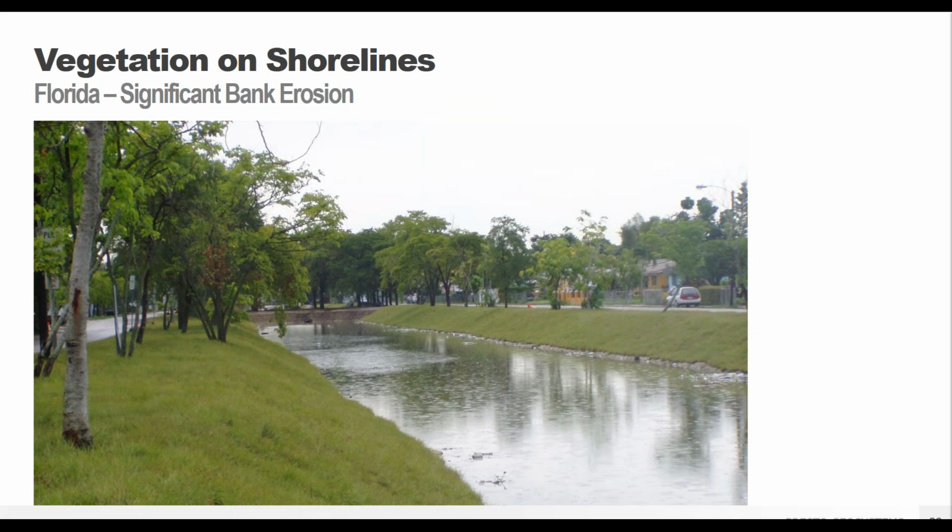Like I said, using a soil and a grass type that's local to the area, maybe even using that salvaged topsoil that you might have if you were regrading your channels, is going to be really beneficial, and it's really going to help blend the whole situation so that the GEOWEB panels aren't noticeable. But now you can walk along this shoreline without fears of it sinking in, and this shoreline is going to be protected against erosion for years to come. So definitely a great outcome.